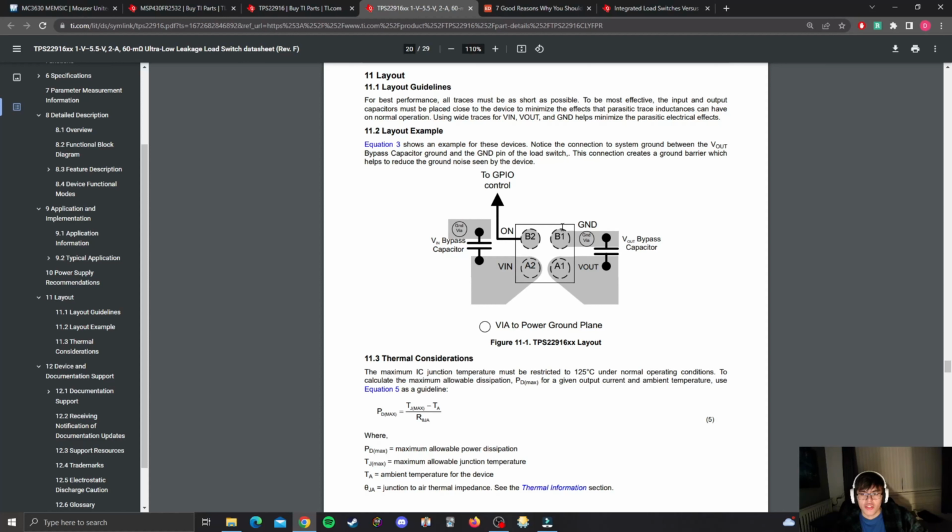B1 was ground, and this should have been labeled ground as opposed to on. So these two were necessarily switched, but because this was always labeled to the PCB header, it was correct at the time. So it was still usable, the switch, although the schematic said otherwise. This must have happened when I designed the PCB, which is very poor and amateurish layout, and let's just say it's very disgusting behavior, really, and should have never been done, should have been double checked. It's probably a stroke of good luck that it still worked, and the package was quite simple.